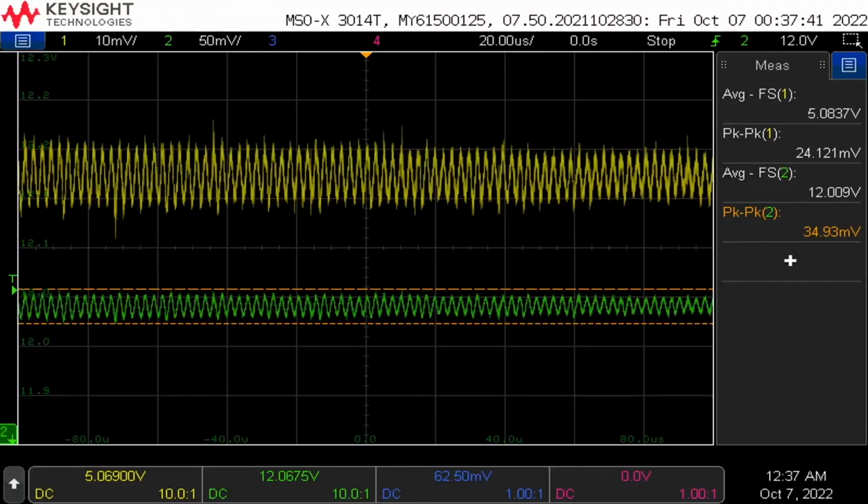This is a screen capture under the previous test conditions. It is clear from this picture that the linear regulator in yellow has stayed within 4.5 and 5.5 volts and is a less than 1% ripple. It is also clear that the power converter in green has output 12 volts and has a less than 1% voltage tolerance.